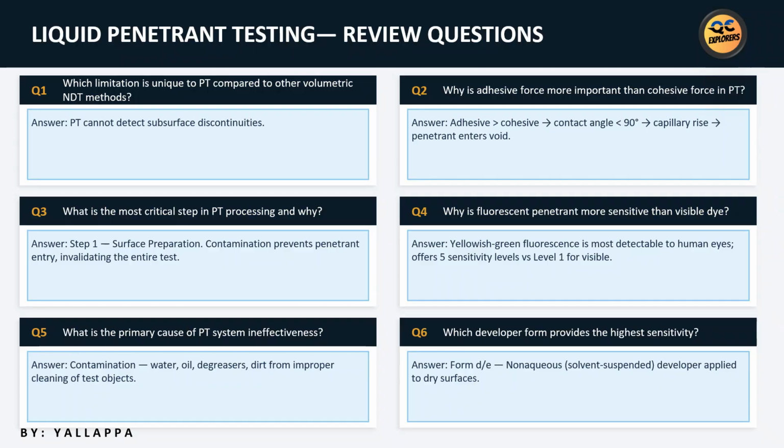Now let's quickly review some important certification-style questions. Question 1. Which limitation is unique to PT? Answer: PT cannot detect subsurface discontinuities. Question 2. Why must adhesive force be greater than cohesive force? Because this creates good wetting, a contact angle less than 90 degrees, and proper capillary action.